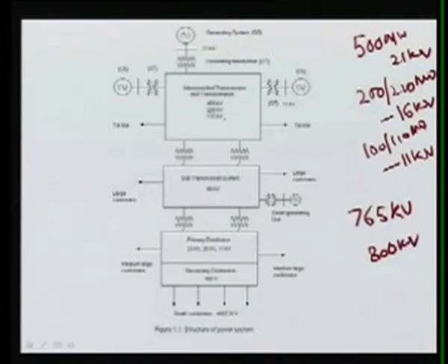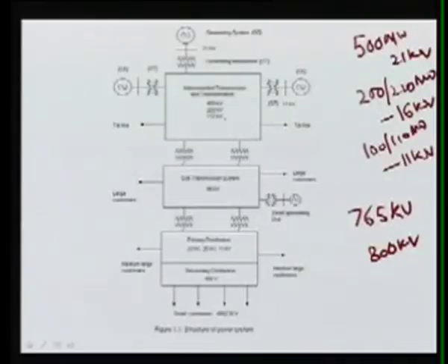transmission system, but presently it is operating at 400 kV. We have the Anpara and Unnao line. It is very near to us. The line is built on 800 kV class of insulation, but presently it is operating at 400 kV, because later it is assumed that more power evacuation will be required. We can then go for the higher voltage. Once the line is constructed, we only have to change the terminal equipment of this rating.